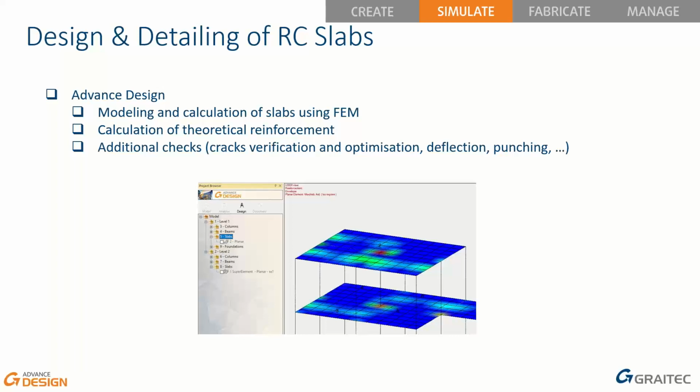For such checks, we could use either theoretical reinforcement values using the equivalent reinforcement diameters, but we can also add info about the real reinforcement by adding info about the bars and spacing on the top and bottom. But it's important that such real reinforcement is not shown and is used for cracks and deflection verification only.